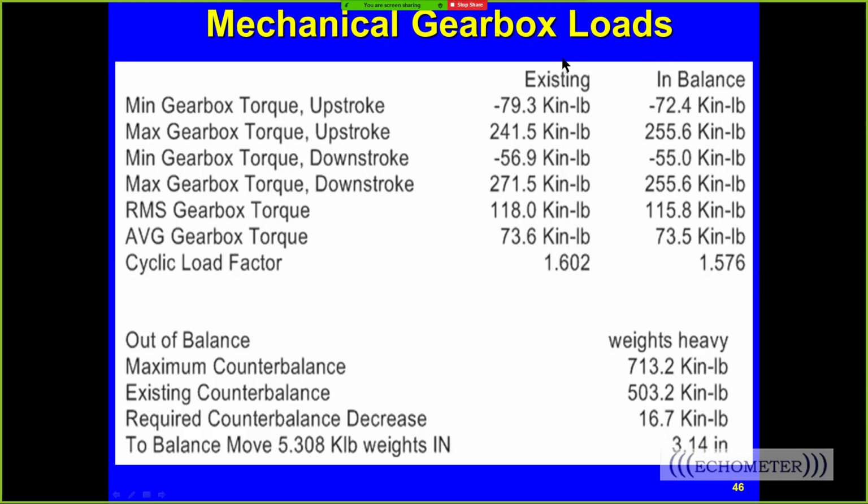Now notice that the cyclic load factor actually went down. Here's balance and here's existing. That means we're going to save some power. And the percentage change here is a percentage reduction in your power bill that you'd make just by putting the weights in the right position.